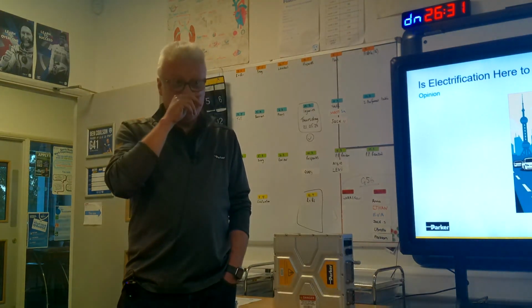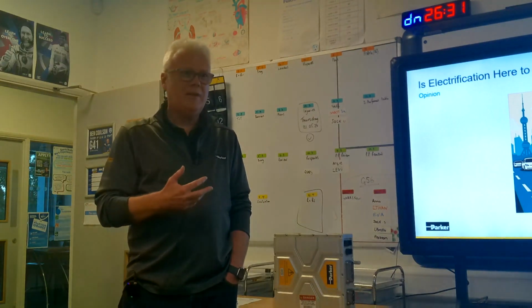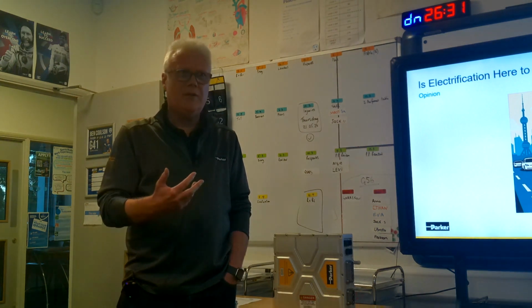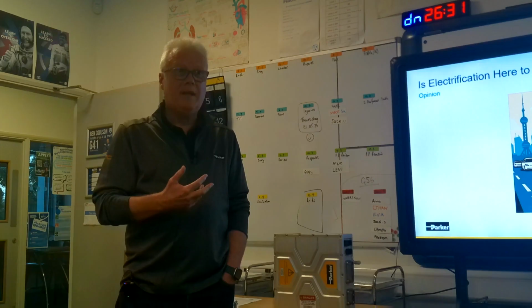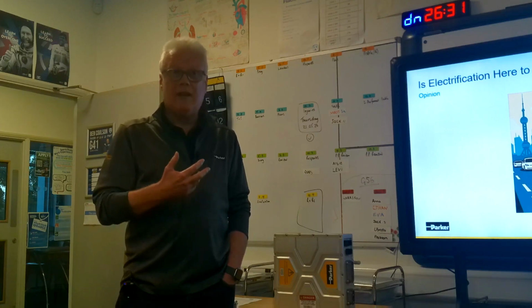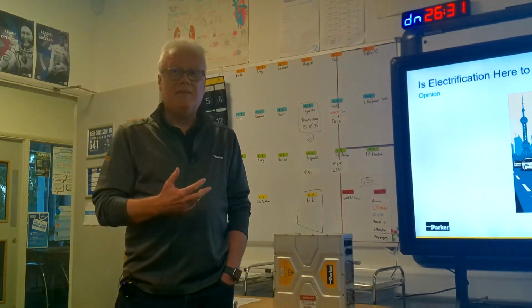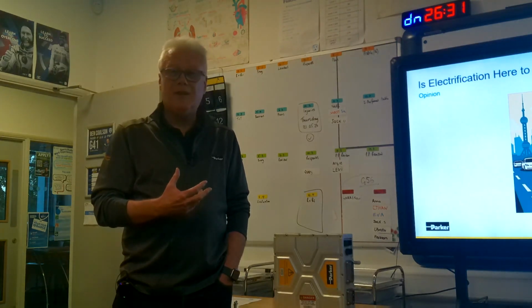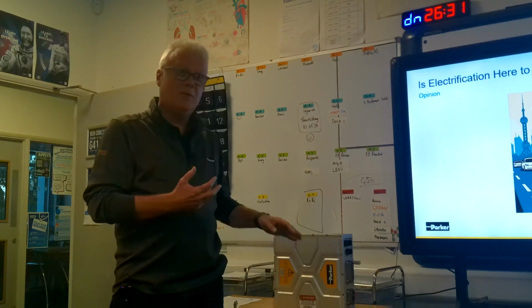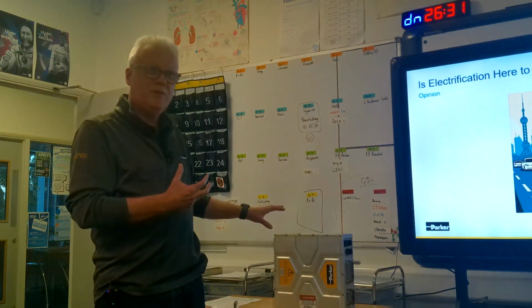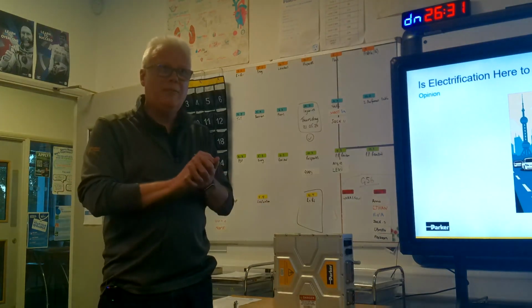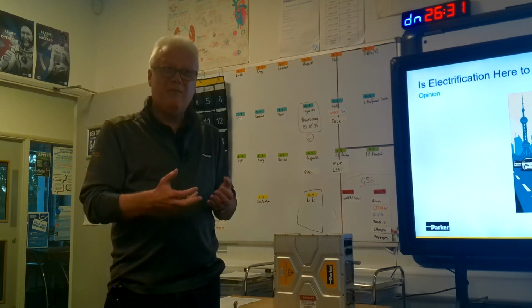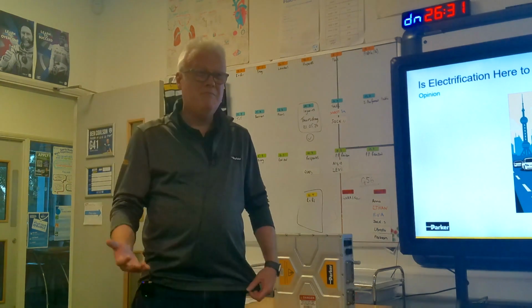But I think the world is changing now. Silicon carbide FETs, which switch really quickly, and you can switch them at 20 kilohertz and beyond, used to be really expensive to buy. Now the volume is there, so they're getting very economical. And you can save on other aspects of your design by switching quicker. Magnetic components get smaller. If you've got EMC filters trying to filter out switching noise, the faster I can switch, the smaller I can make these things. So the future is, we're on that cusp of changing switching technology, and we're going to end up switching quicker anyway. It will be 20 kilohertz plus.